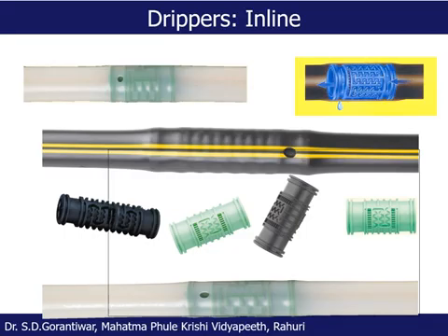Another case is a crop like sugarcane, for example. During the earthing up operation, we have to move the lateral from one place to another place. So whenever there is movement, we have to use the inline kind of emitter.